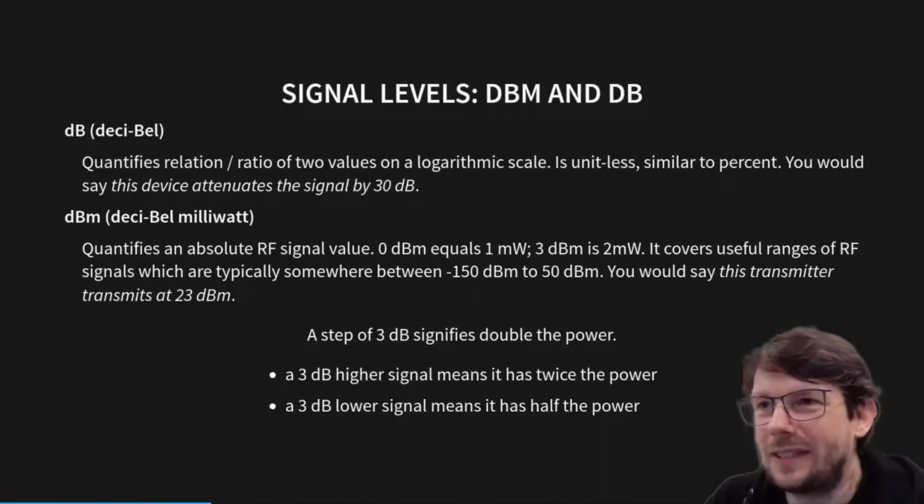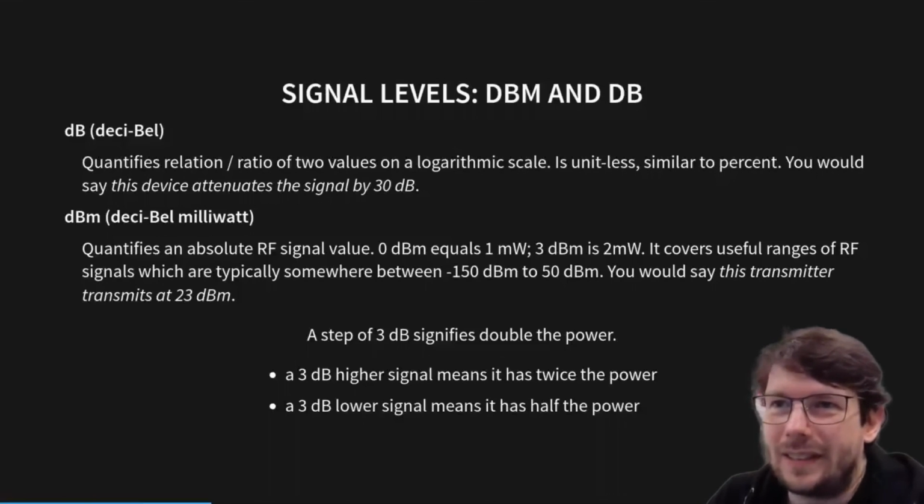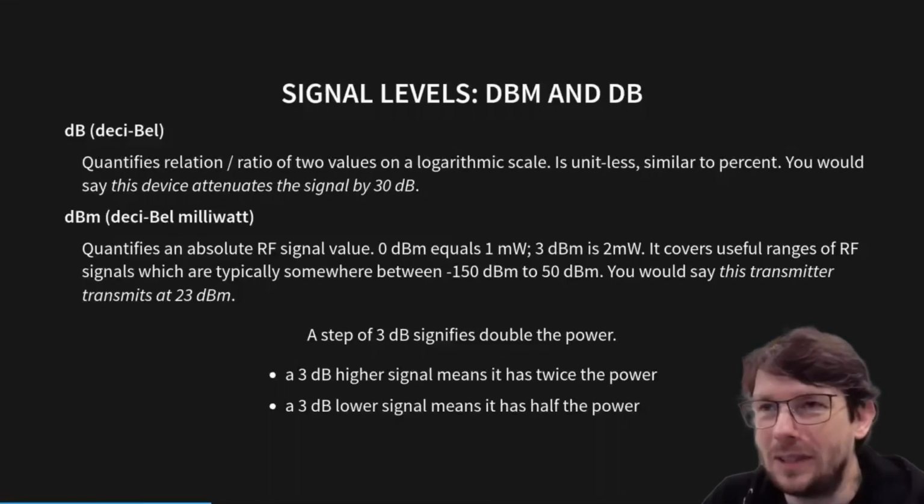So it's always in relation to something. It's a relative measure or ratio that you always need to apply to some base value in order to have any meaning of how much it is actually talking about, and not just a ratio. So you would normally say things like this device, let's say it's an attenuator, attenuates the signal by 30 dB. So you know what goes into the device is attenuated by 30 dB at the output, but you don't know anything about an actual signal level, because that, of course, depends on how much you put in, right? So whatever you put in is attenuated by 30 dB in this example.